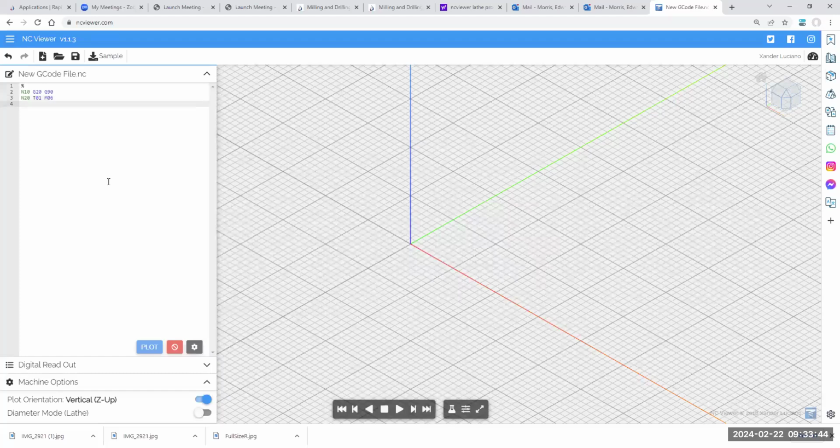Now we're going to go to our first coordinate using the Cartesian coordinate system. In N30, we're going to have X -1. You remember that circle where we're off 1 inch of the part? That's the -1 direction, so -1.0 in the X. Y0 space Z1.